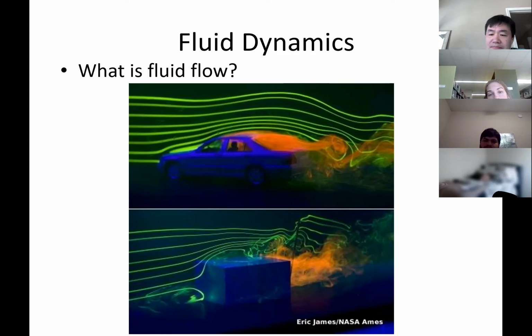Anybody? Would it be because there's a lower velocity back there? No, it's not. Lower velocity would be high pressure. That's Bernoulli. Okay, the velocity is about the same. How much in, how much out, doesn't matter that much. It might change a little from place to place, but the major reason for the low pressure behind, just like I said here.